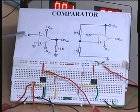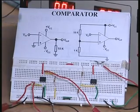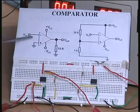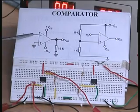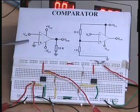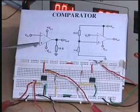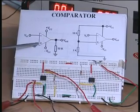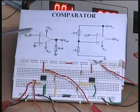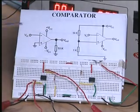I already explained to you, whenever the sine crosses the 0 and increases by even 150 microvolt or so, immediately this voltage will be larger than this voltage, and therefore it will go to minus VCC. Whenever this voltage goes below 0 by about 150 microvolt, again this will become less compared to this, and therefore, because this is larger, it will go to plus VCC, and so you will get a sine wave converted into a square wave, as I have already explained to you.